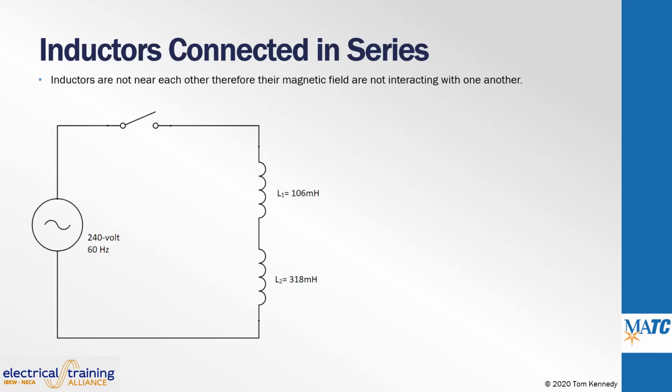In the figure of this inductive circuit shown here, there are two inductors connected in series. One item of information to note is that the magnetic fields of the inductors are not interacting with each other in any way. These are two inductors that are placed at a distance apart, to which the magnetic fields will have no effect on one another. Each of these coils of wire will produce inductance and oppose current flow in the AC circuit. Think about the factors that affect inductance.